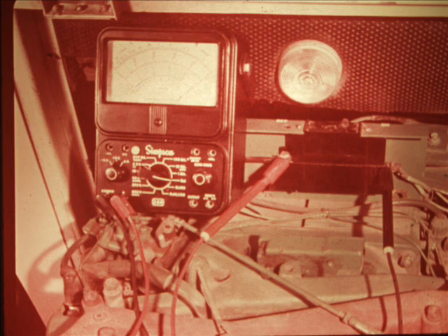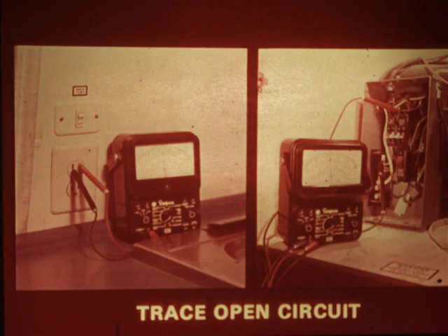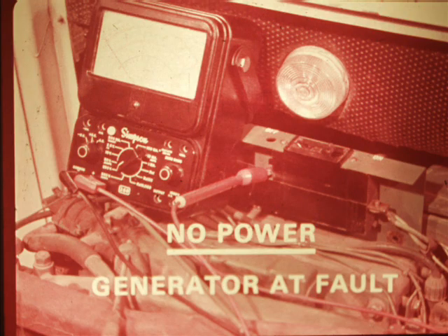So with the breaker on and generator off, check across the breaker with an ohmmeter or self-powered test light. If there is continuity at the breaker, then to locate the open or short, trace back through the circuit in question and to the circuit breakers in the electrical compartment inside the motorhome. If, when you test the generator side of the circuit breaker with the breaker open, there is no power, you will know that the trouble is in the generator, and the generator needs to be tested.